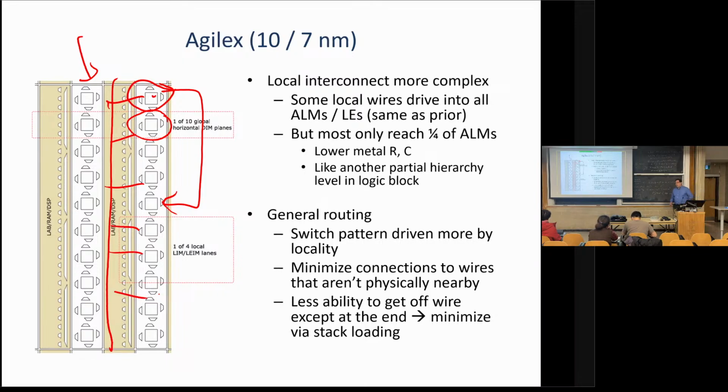Now, if you only had short wires, you'd have to bring it in 5 times to get to all the places you need, and you'd have to push that back to the previous muxing. And you could do that. That is an alternative. You might have to bring it in 5 times on 5 different inputs. But that is costly as well. I've just burnt 5 muxes and in the end I still had to drive 5 different pieces of metal. So at least in Agilex, I'm not on the team. You're probably closer to the team than I am at this point.